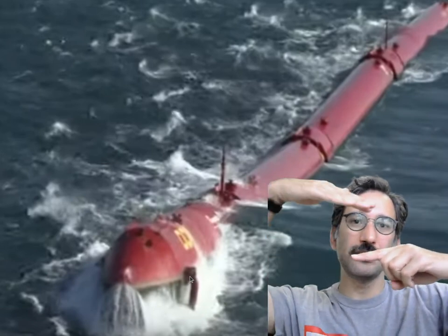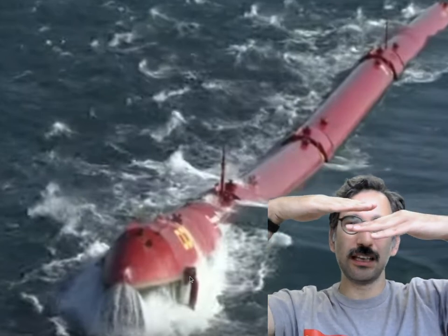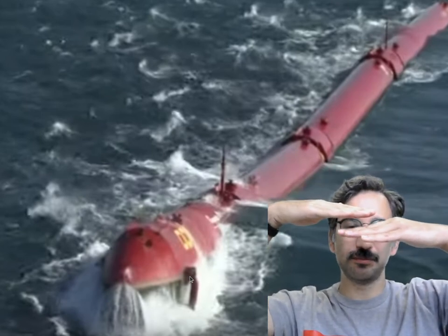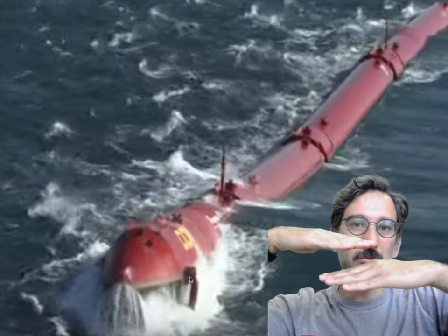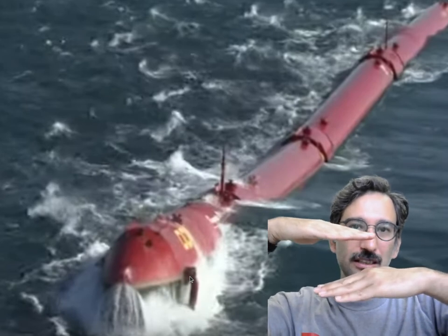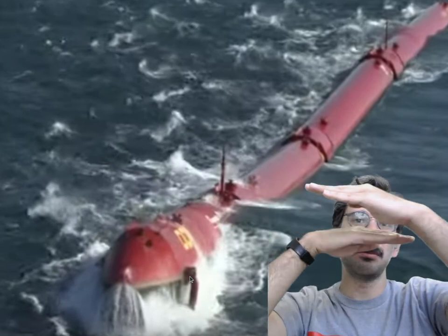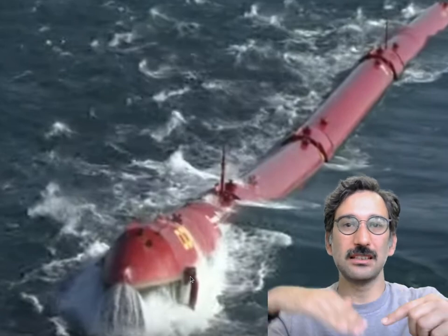First, the waves are coming, so the Pelamis device is submerged under the water. Then there's a phase difference, then it goes up, the wave has already passed, so it will go quite a lot out of the water. So the phase difference between the actual movement and the waves determines the mechanical power flow between these two devices.